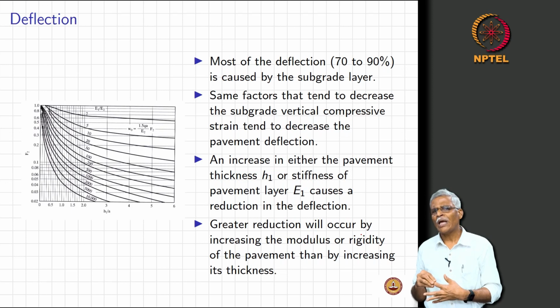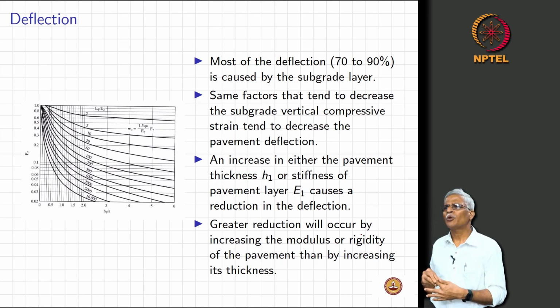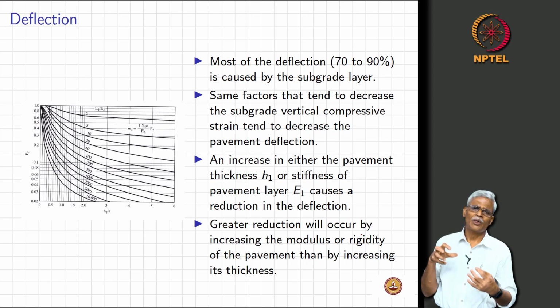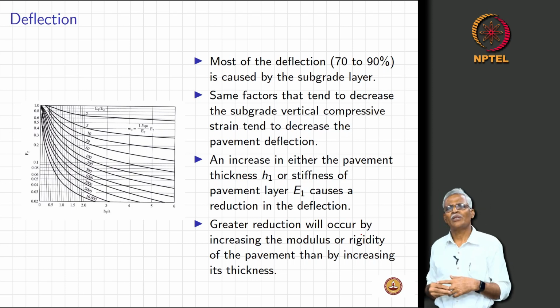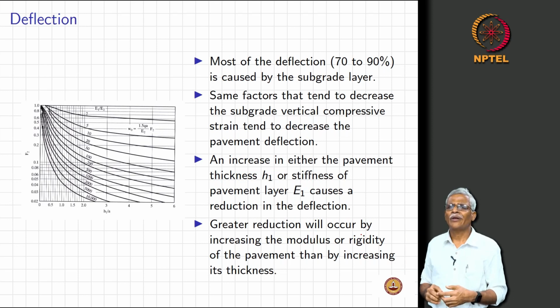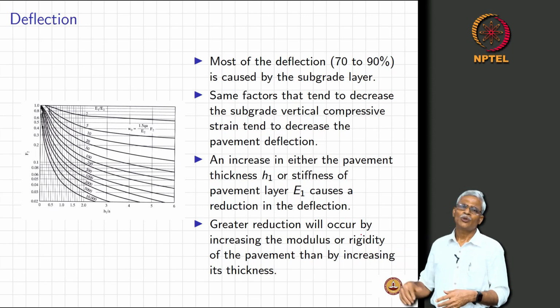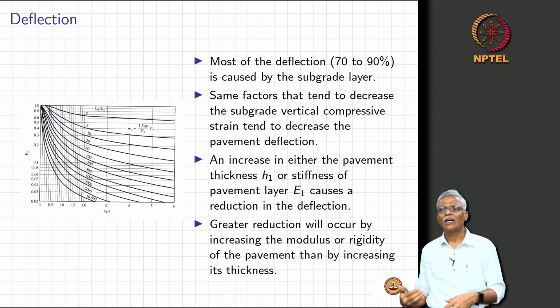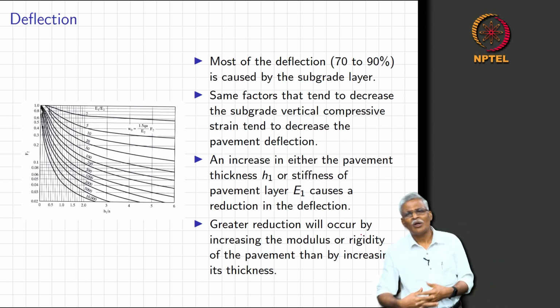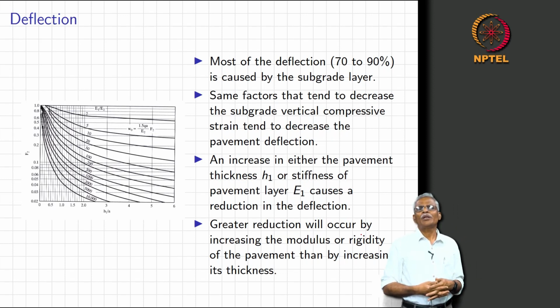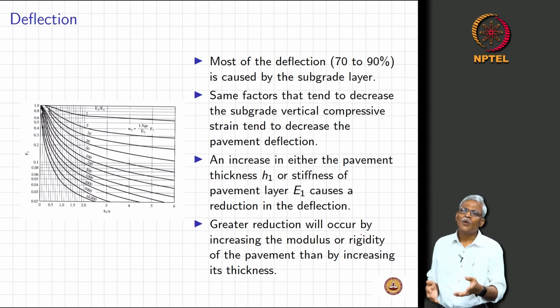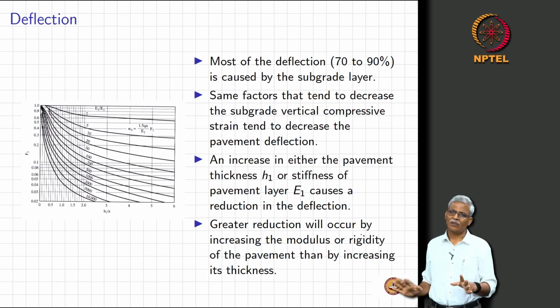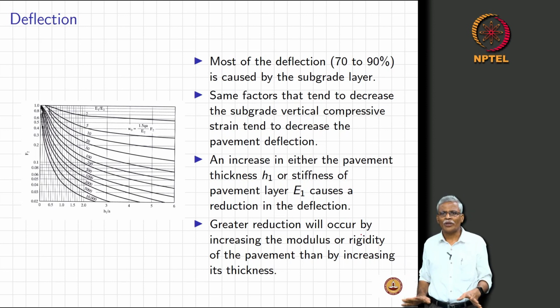Now, do you say, I think they have not put the required quantity of bitumen, so you take a core and check the mix design? The mix design seems to be fine. Then you say maybe they did not put the required thickness. You take a core again and measure, and the thickness is correct. Unless you take a core completely, or do a cut and see, or do some kind of non-destructive testing, you will not be in a position to say which layer of the pavement has actually failed. This is the most important point here.